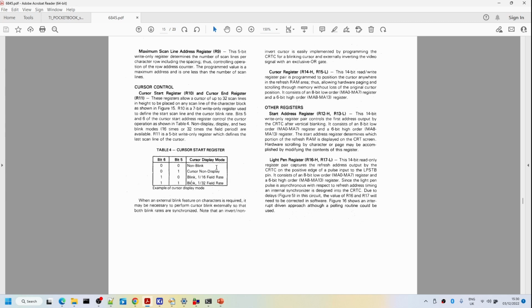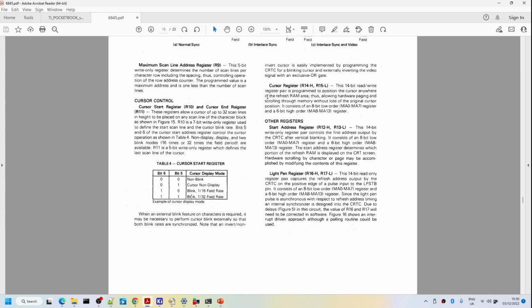And then the other 2 registers that are also important: once we've enabled the cursor, it will default to the top left hand corner, which is 0, 0. But by changing the value in the cursor register here, it should move to, say, the 10th character, or the 80th character for the end of line, or number 81, then it will be the next line down and 1 character in. So we can make sure that the cursor is moving around as we expect.